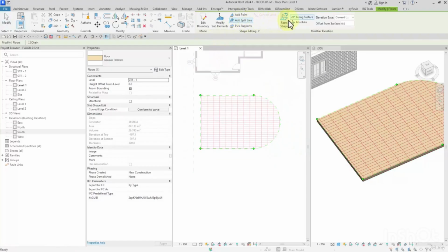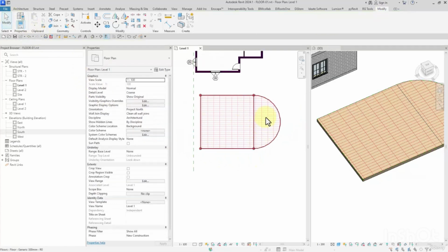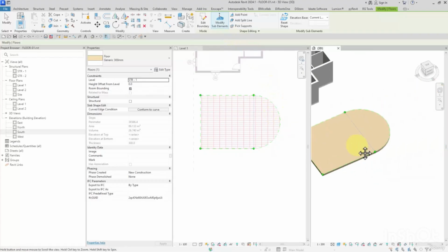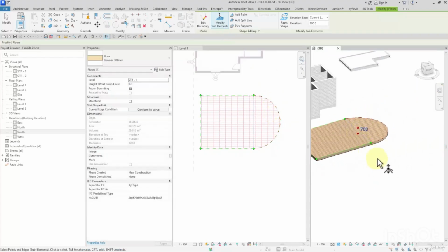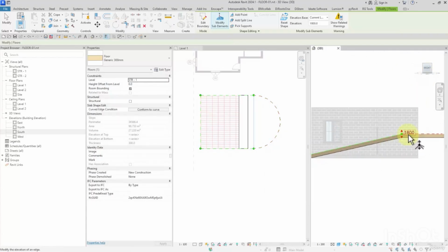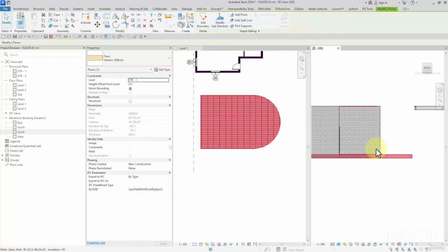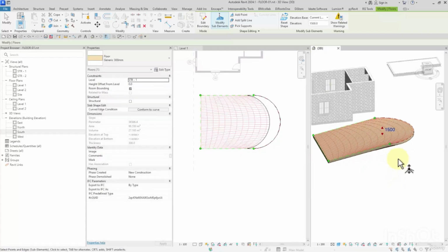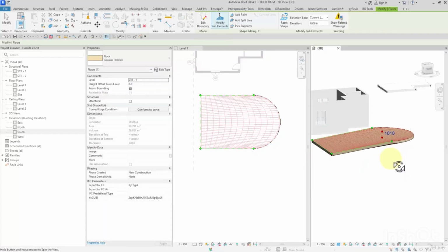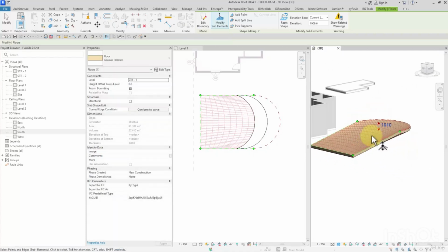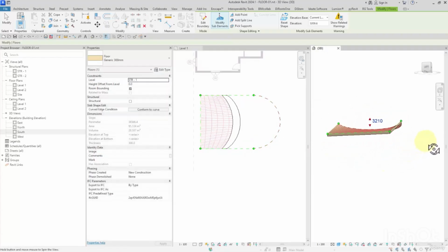like this way. Again, I click on a split line and then draw a line or a linear edge. Selecting the arc, if I select this arc, then I can move this upward. Watch this. As you can see, this is its appearance. If I reset it and select the line and move it upwards, watch this. This will be the result if we do not add the split line. Watch this. Here we got an arc like this way.